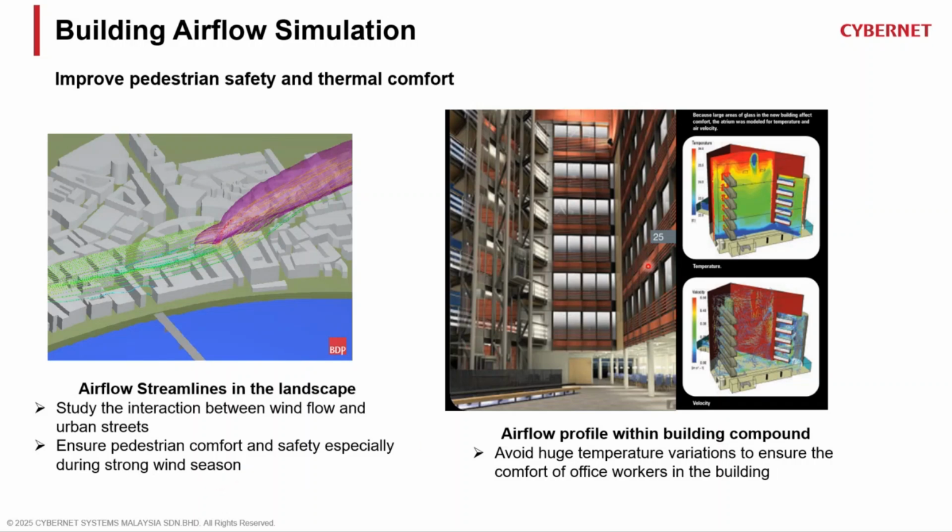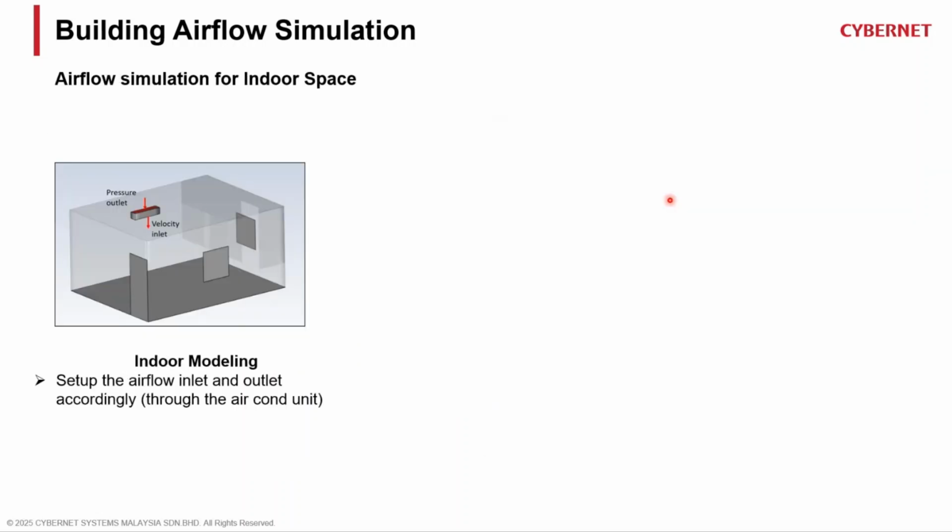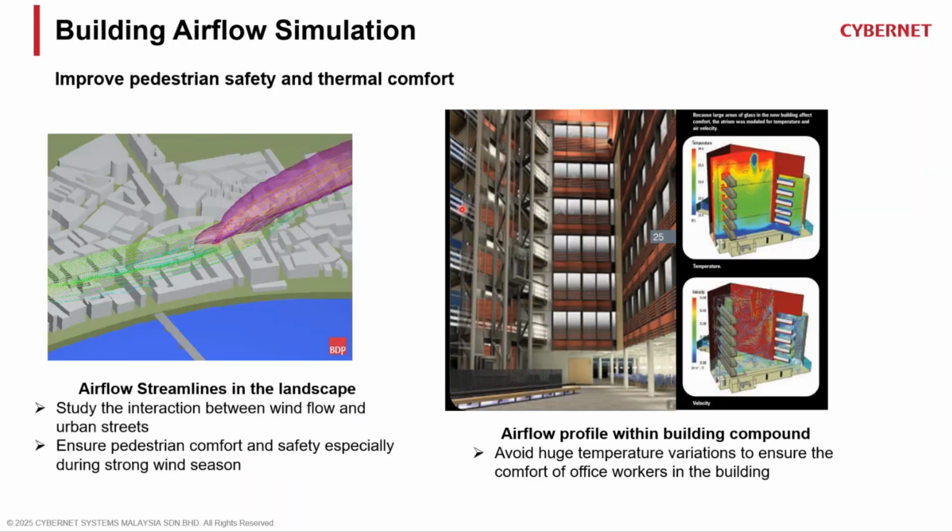Okay, and in terms of an office building, there's going to be a lot of people walking on the open space area. So obviously you will have the outdoor units discharging heat as well. By doing this kind of simulation, you get to know if a certain area is getting too hot, let's say in the walkway here. If that is the case, then maybe you have to think of a way to shift or put the outdoor units in other places. This gives you the insight to better install or configure the setting properly.